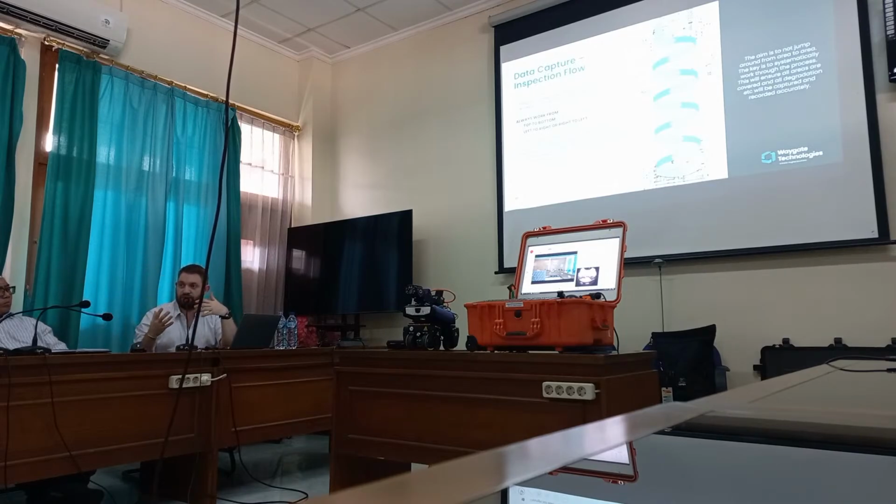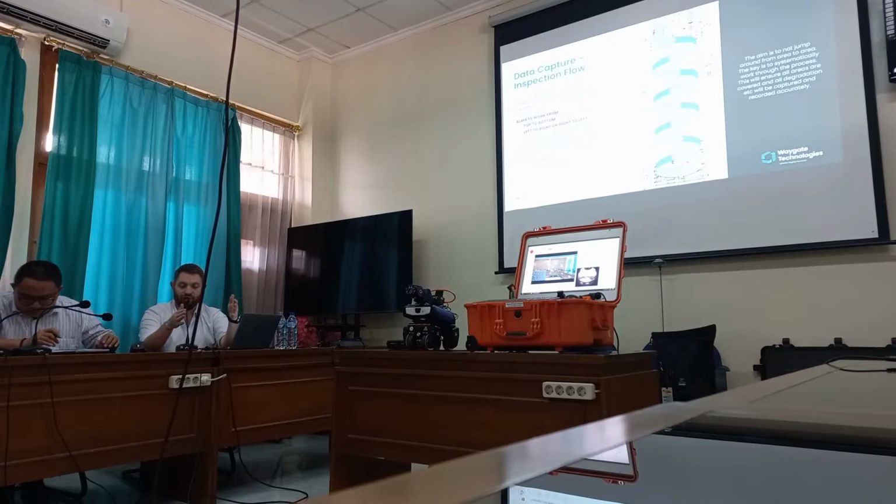When you're reading the report at the end, the image looks unstructured and the chances that you've missed something is a lot greater. So we want to be working in a methodical manner, such as like you would read a book. So perform the inspection from top down, left to right, or from right to left. But once you've chosen your appropriate inspection task or method or way that you're moving, stick to that for the entire asset.